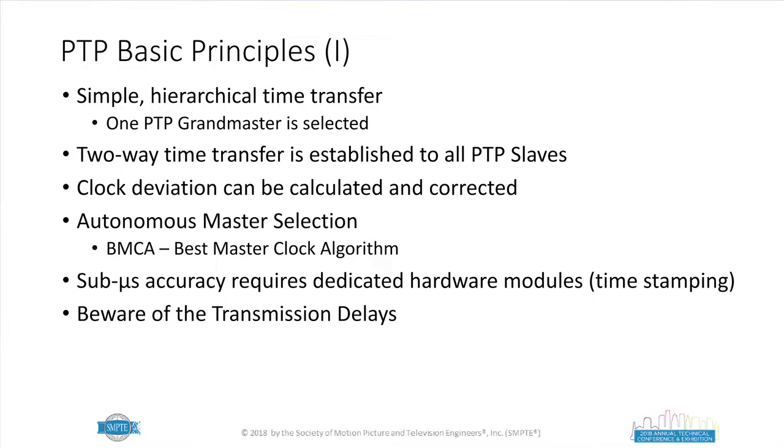If it's well implemented, it uses the best master clock algorithm, and in order to reach sub-microsecond accuracy, hardware-based timestamping at the network card PHY, it being an FPGA based or a regular NIC based, is required. There are operating systems which don't support hardware timestamping right now, Windows specifically. Linux, it's not a problem, although the next revisions of Windows do introduce PTP, by the way, but it's still software-based timestamping. So, you know, we've still got some time to go before there is a common understanding on how to do that on the Windows platform.